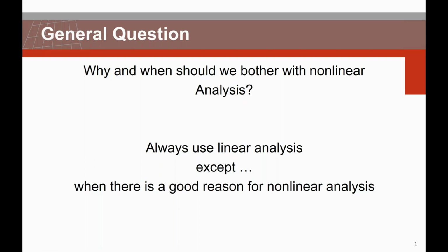And of course, the first question to answer is why and when should we bother with nonlinear analysis? The general answer to this question is always use a linear analysis, except when there is a good reason for nonlinear analysis. Indeed, performing a linear analysis is much easier than performing a nonlinear analysis.